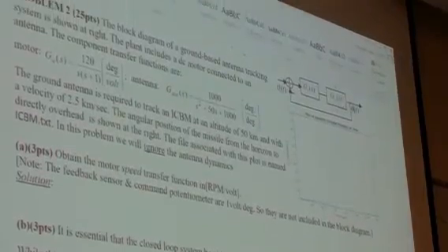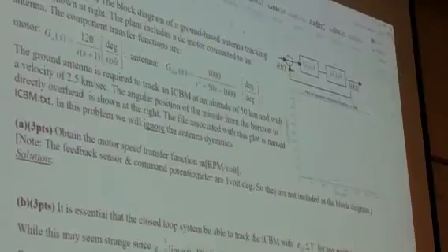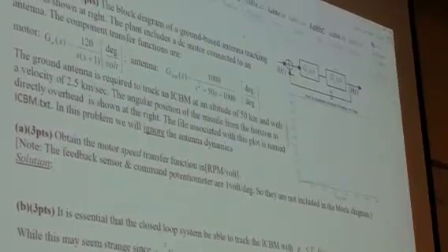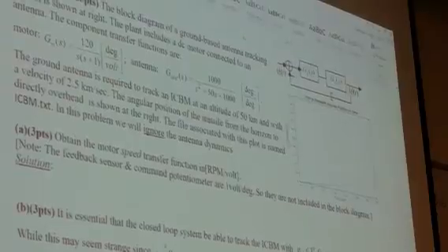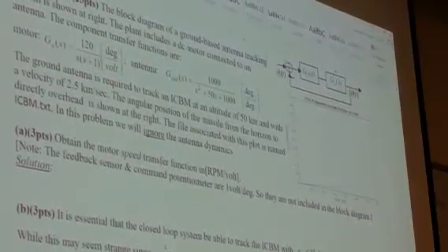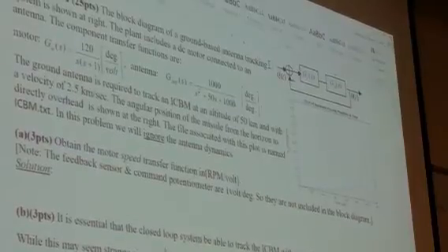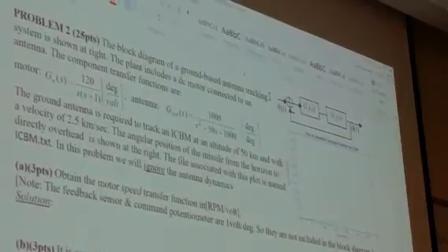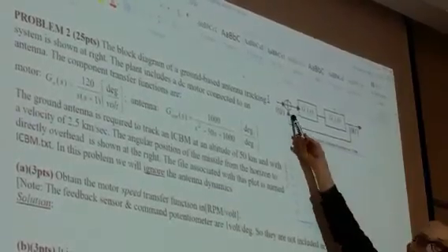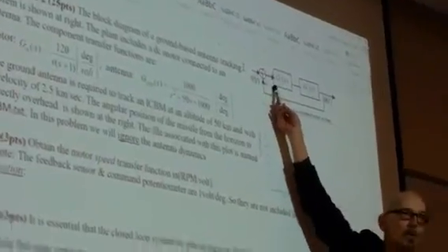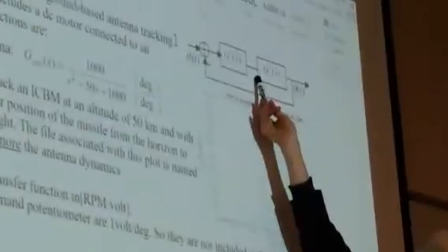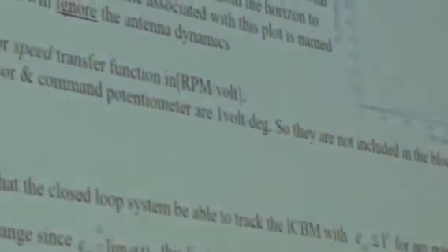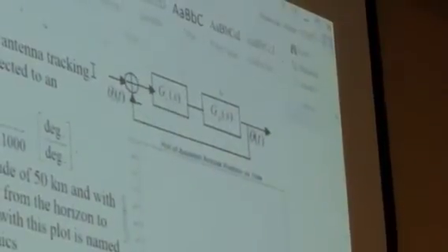So when you're measuring this, you're measuring it with volts. It's degrees, but you convert degrees to volts. And then when you put this reference or command input in, you want to put degrees in, but when you turn the dial or whatever, it's volts. So really what's coming in physically is volts. And what's operating the controller is volts. And what's going out of the controller is volts. But because I wanted to make the problem easy, I said, just suppose it's 1 volt per degree. Then we can basically look at all of this as just degrees. But understand it really is volts.